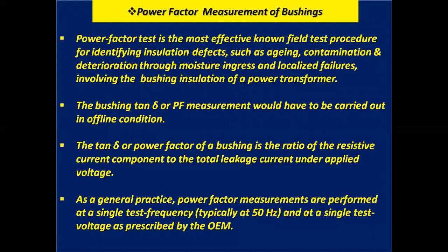Let's start with the power factor test on bushings. Power factor test is the most effective known field test procedure for identifying insulation defects such as aging, contamination, and deterioration through moisture ingress and localized failures involving the bushing insulation of a power transformer.